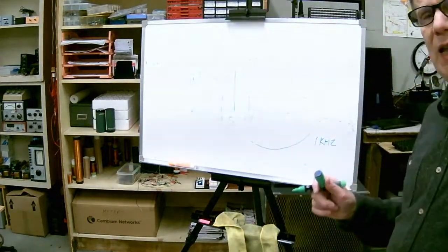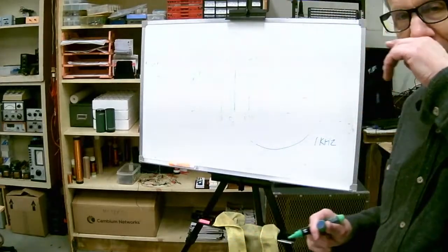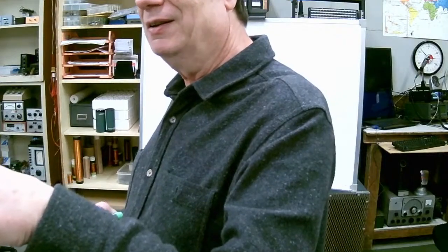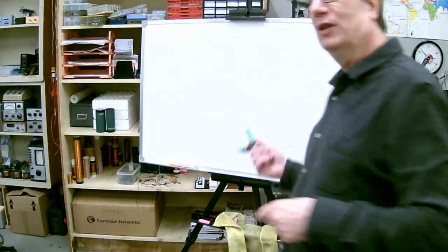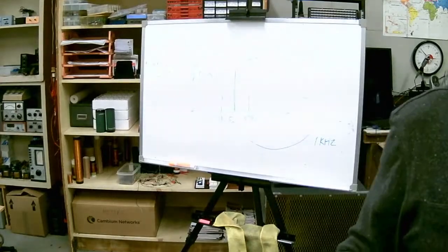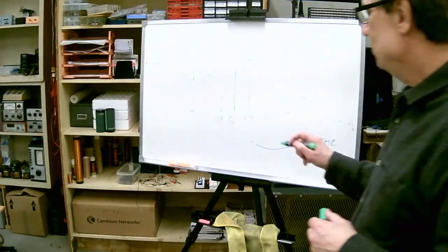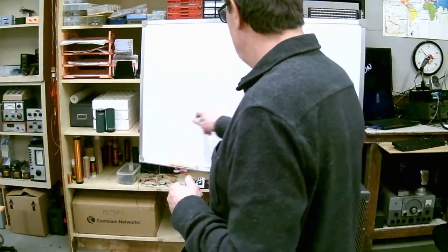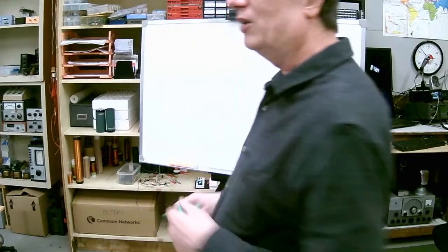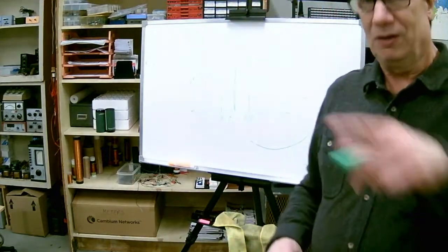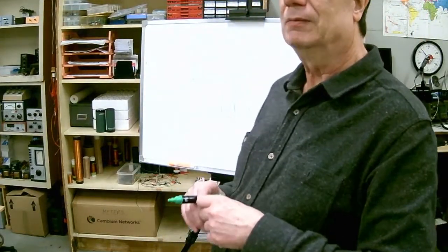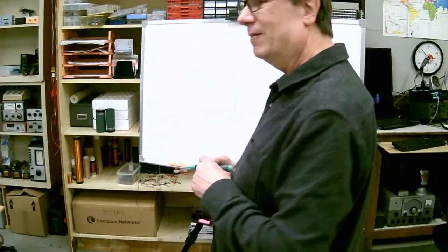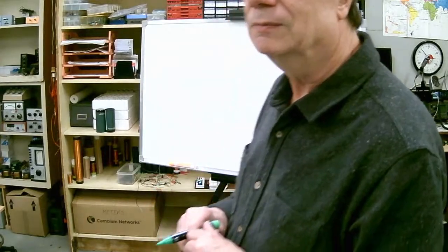Is that what we saw here? No, that's different. You're only seeing amplitude versus time on that. You aren't seeing amplitude versus frequency. A spectrum analyzer can. So explain the difference to me. On a spectrum analyzer, the horizontal axis is frequency, and on the oscilloscope it's time. It's going to look the same, it's just different information. Right. I'm going to have to think about that.